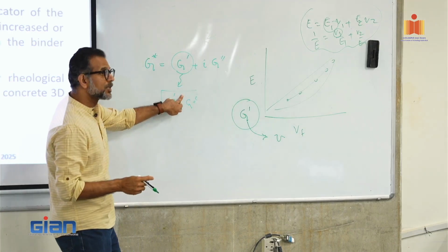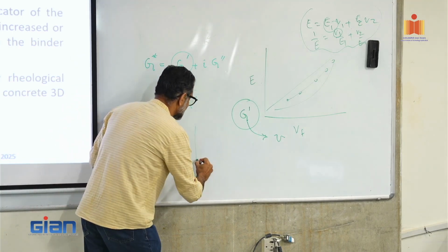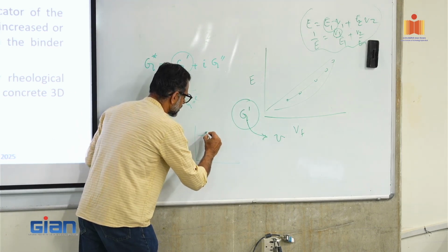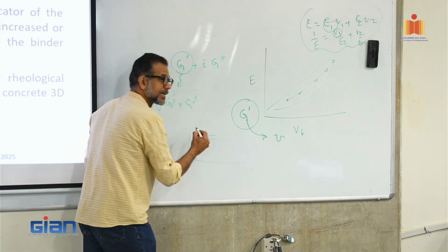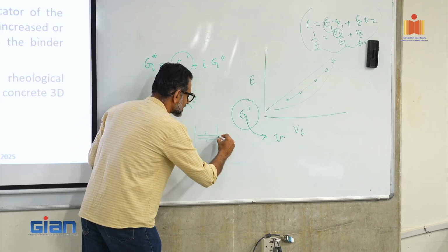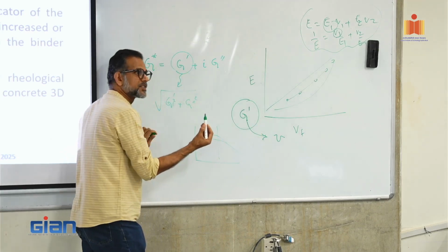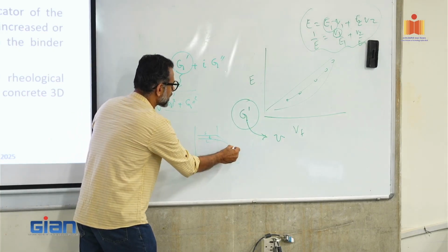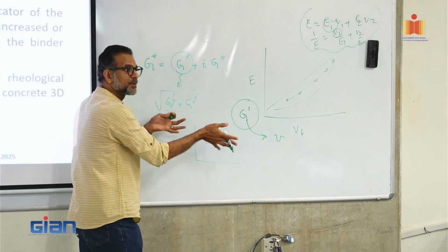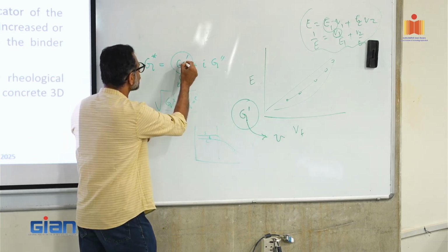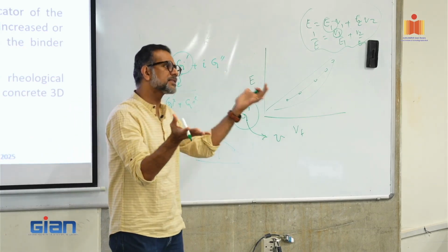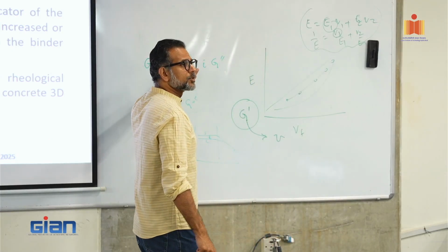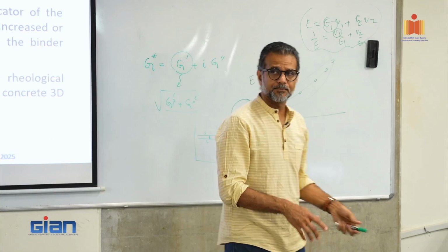But the problem with using loss modulus is, you remember yesterday I showed you the transitions. The linear viscoelastic range is where your storage modulus is like this and the loss modulus is like this. Beyond the linear viscoelastic range, things kind of change. So if you start to do this, you don't have this much of difference because these things are kind of overlapping. The balance will go away. But if you just do this, you will see some clear differences and you can keep that. Either way is okay, it really doesn't matter. But it's so easy to just pick this one value and use it, right?